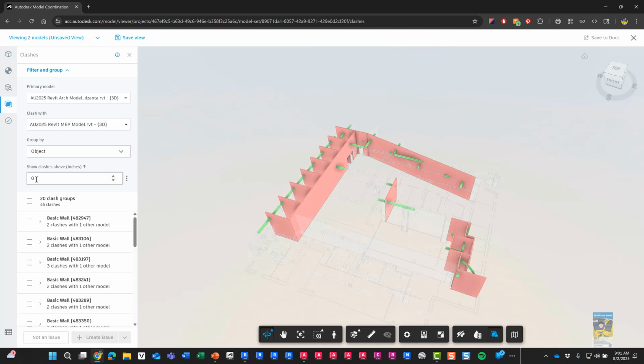Okay, think of it like you know how Autodesk Navisworks Manage gives you the ability to do clashes that are soft clashes, where the objects just brush against another object, or if it's within 1 or 2 inches of clearance, it's considered a quote unquote soft clash. It just depends on how you want to look at a clash and how you want to classify it for the purposes of investigation and coordination against other disciplines.